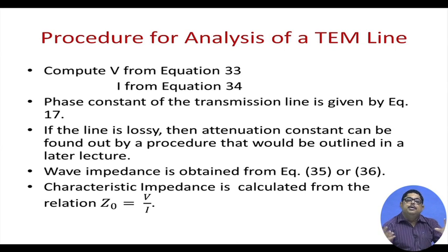Basically, characteristic impedance is defined for a symmetric two-port network. Any symmetric network, what is characteristic impedance? Actually any general two-port network, even non-symmetric, has image impedances. What is image impedance? Suppose I have a source resistance and some load, such that from the source side the input impedance is matched with the source.